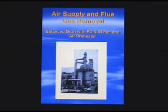The intent of this is to reduce the amount of fuel gas that you have to fire, because whatever is going up the stack is basically lost to the atmosphere. So the more heat you can recover from the stack, the more efficient the unit is. The one drawback with these is that your stack temperature is limited by your gas dew point of about 300 degrees Fahrenheit. So you do not want to cool it down below that. Otherwise, as the flue gas rises, it may condense, and you could have acid gas forming inside the stack to cause accelerated corrosion.